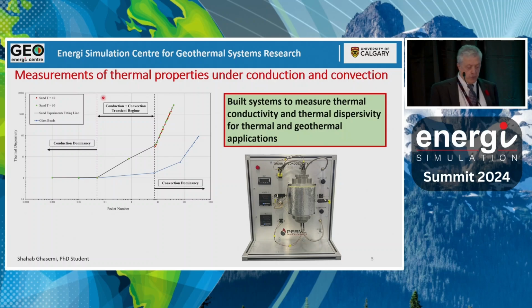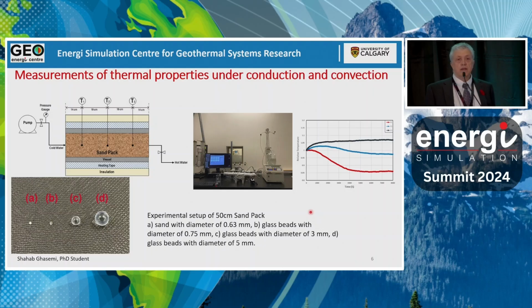Well, we start with the property of thermal conductivity, and this is the device, the steady state method of thermal conductivity. So we put heat load, we measure temperatures, and then we take the same exercise and put it in a not so good looking core rig where we have a core holder, and in that core holder we have a porous medium. For this specific set of experiments it was sandpacks.